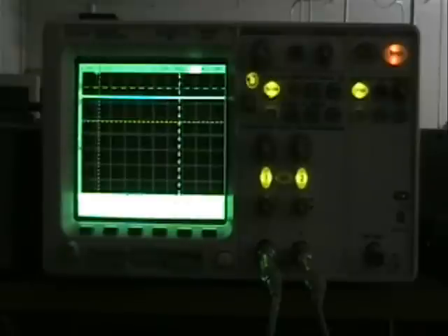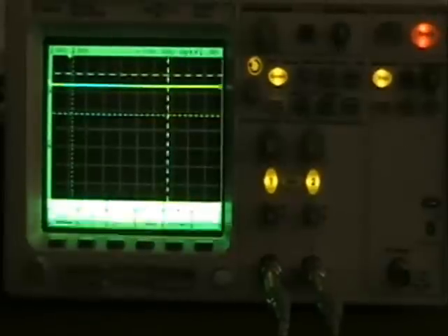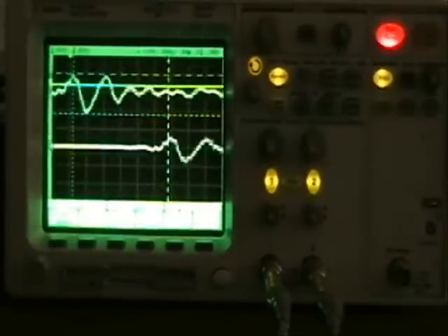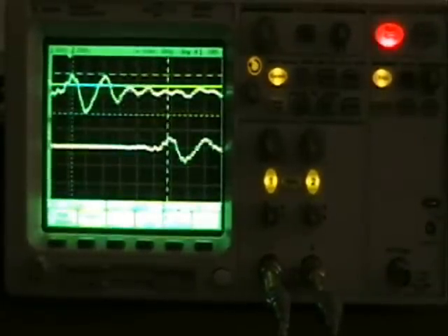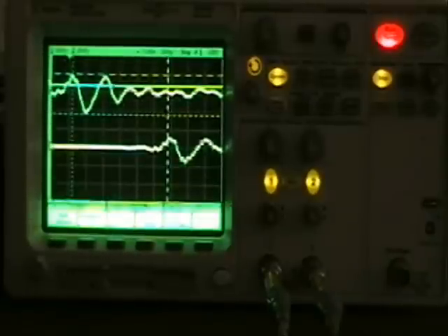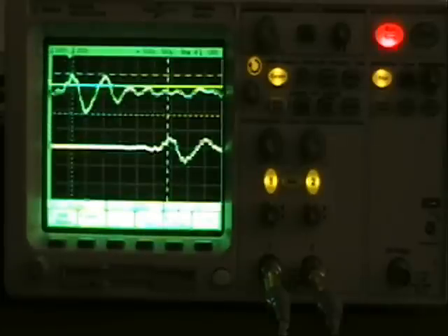The scope is in single sweep mode as indicated by the yellow light under the single button in the top right hand corner of the scope. A hand clap to the side of microphone 1 away from microphone 2 triggers the scope, indicated by the run button, which turns to red when triggered, when the acquisition is completed.